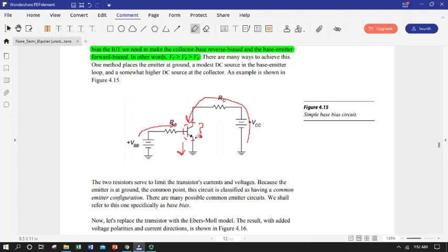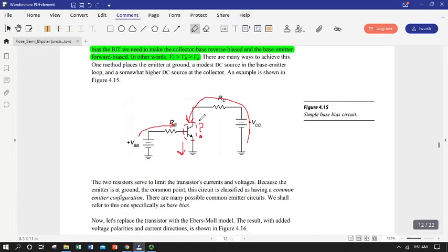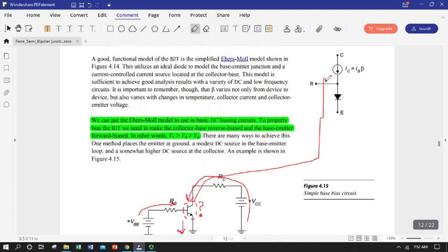Because we know we can't just treat it like a resistor, we can't treat it like a capacitor. How do we basically replicate those crazy voltage current curves in a practical circuit? So the way we do that is to use a model. We take everything in this dotted circle, this whole transistor, and we represent it with something that we can use.